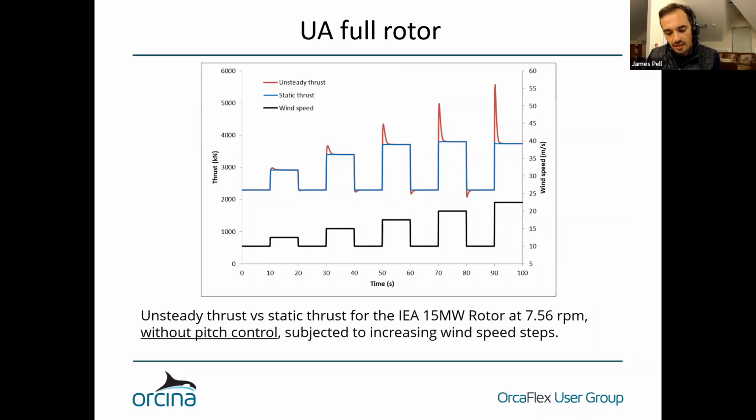And as an aside, one thing that we've learned looking at that model is that the reference wind turbine, the 50 megawatt, actually has an aeroelastic instability when you include a torsional degree of freedom in the blade, which is naturally always included in an OrcaFlex model. So it always holds the full 6 degrees of freedom.